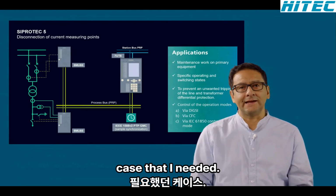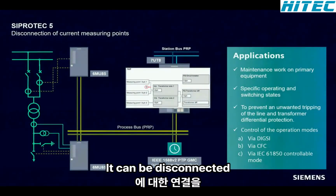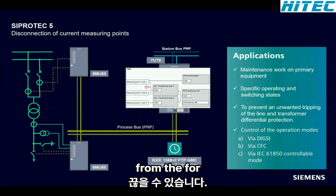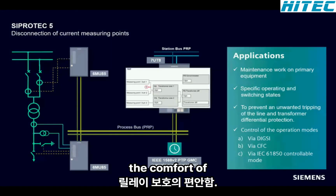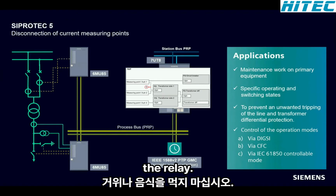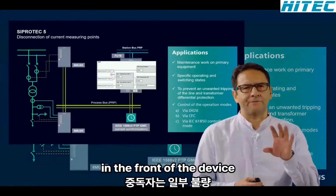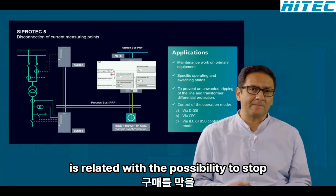In case that a test is needed in one of the measuring points, it can be disconnected from the function group transformer side 1. And if a test needs to be done in the merging unit or in the circuit breaker, for example, primary injections, the disconnection of the measuring point avoids the wrong operation of the differential protection. How to do that? It can be done via binary input of the relay, or it can be done via GOOSE or a function key in the front of the device, also using IEC 61850 controllable mode.